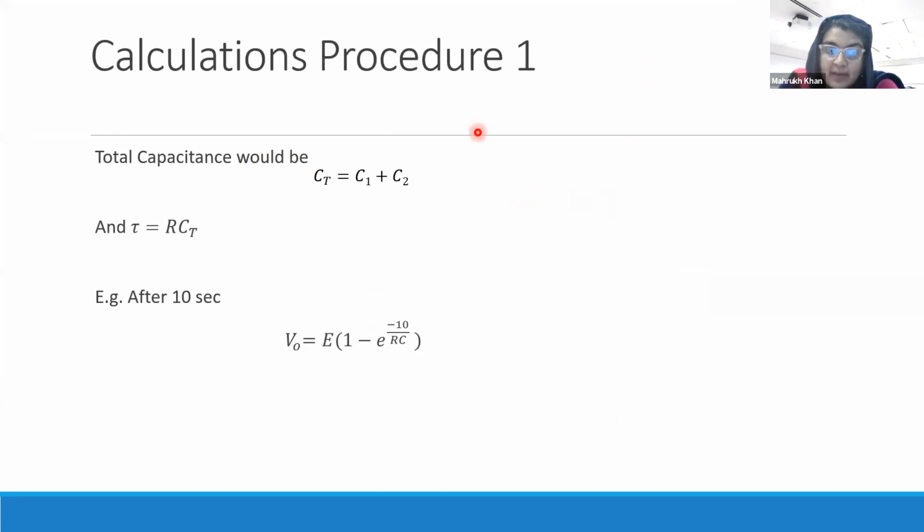That's good. So what I'm seeing here in table 16.2 is that for all the seconds, you will record the voltage across the capacitor and VR. VR, you don't have to measure. What you just do is record VC, the voltage across the capacitor, for all these seconds, and just do E minus VC. That will give you VR. So it's okay, you just use the measured values to calculate a measured VR. And then you will plot the graphs on 16.1, and you will label what is 1 tau and 5 tau.